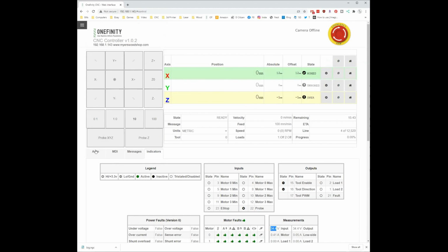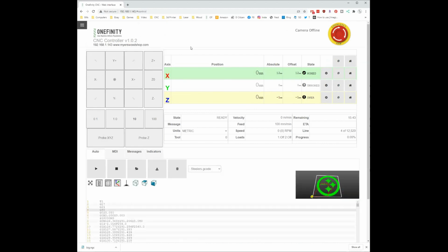So have you had any issues with the probe moving, since it kind of goes from the top right instead of the bottom left? No, nothing. I like that too, because if for some reason your probe doesn't make that connectivity, I have had this on the Shapeoko where it goes the opposite way. I've snapped bits because it just kept going and the bit snaps and there's nothing to stop it.